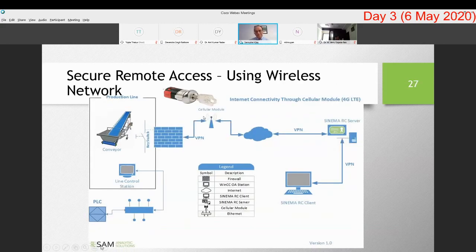This is actually a physical key. What it means is that the network is segmented and no bad actor actually can get into the network until an operator inside physically turns on the key, which basically there's a breaker and that allows the key switch to operate and close the breaker and give the access to the facility's OT network.